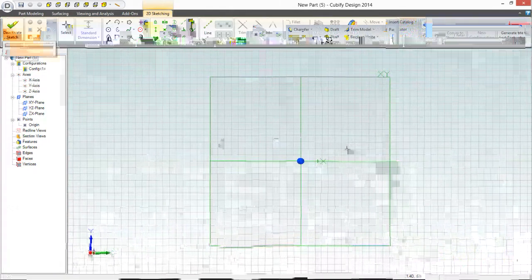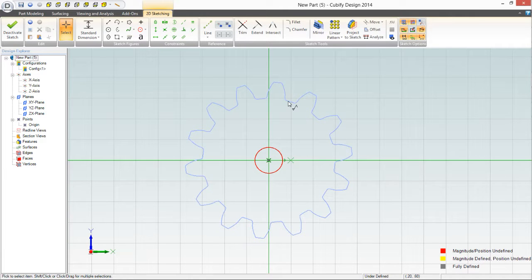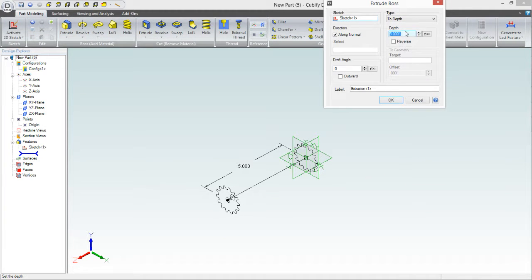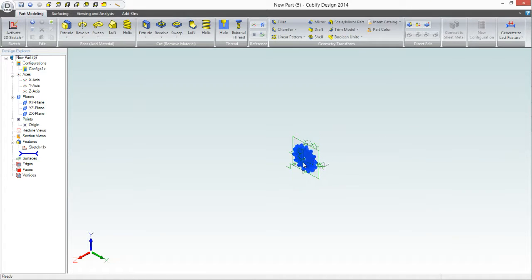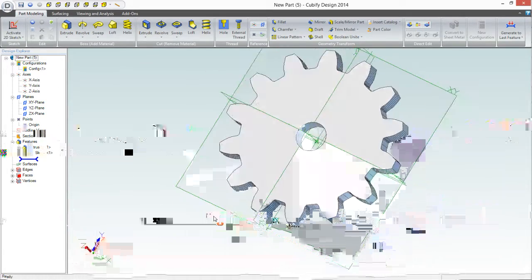Now I can paste, Control V, and there's my circle just perfectly set right in the middle, snapped right to it, because it's a polyline. Now what we can do here is we can just do a simple extrusion of these parts. And let's say that I want to go to extrude, and the thickness of this part, it'll be a 1/8 inch gear, 0.125, and hit OK. And there's our part. We now have an 1/8 inch thick gear, and our 3D printer can print that just fine.